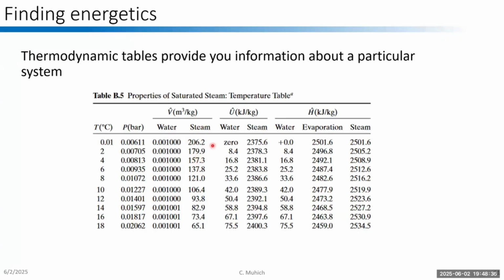Steam obviously is much bigger. It takes up way more space per kilogram compared to liquid water. I also have the internal energy and the enthalpy. And we'll see that a lot of times these thermodynamic values are all referenced to 0 degrees C. However, it's important to always find out where our material is referenced to.